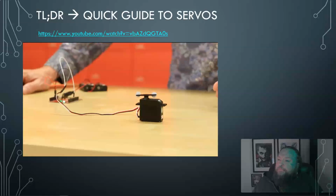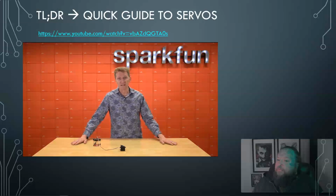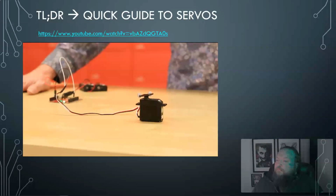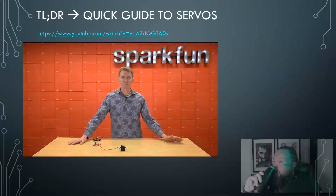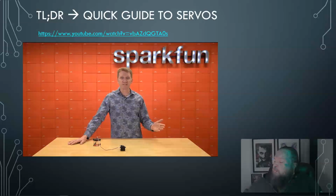So as you can see, I'm controlling direction and speed on this continuous rotation servo, but like I said, the trade-off is position. I have no idea what the positioning is, which for some things might not be terrible. If you want a camera that sweeps the room, you could certainly use something like this attached to a pulley with a slip ring. The continuous rotation servo is controlled just like a regular servo with servo.write. However, with a normal servo, you would send it a number between 0 and 180, and that would determine its position.